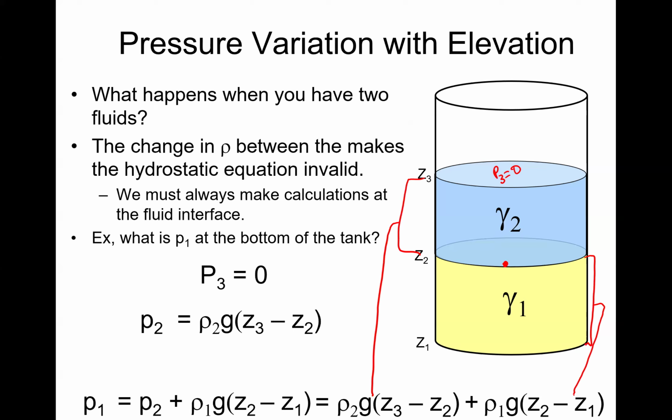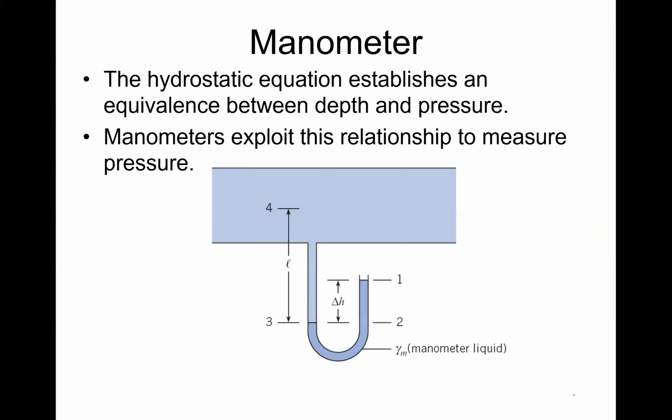And the reason why I'm explaining this is that this is a very common calculation that is done for a manometer. A manometer is typically a system that is used to measure the pressure differential between, say, this pipe, which might have a fluid moving, and a static system that is happening at the manometer itself. So you have a liquid that is typically denser than the fluid that you're working with and is immiscible in that fluid. And you have this differential as you see here.